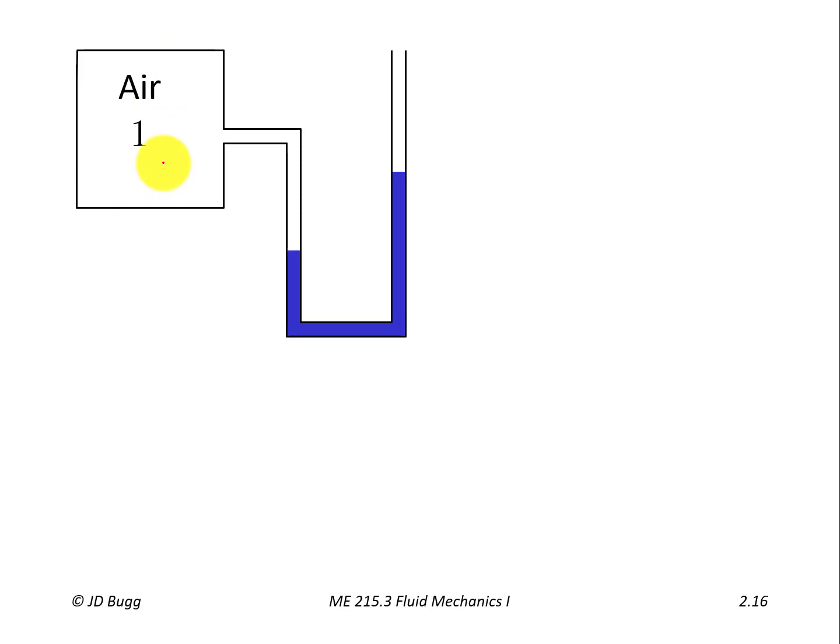If this was at a pressure lower than atmospheric pressure, then the deflection in these two legs of the manometer would just be switched. Some things that are important here: the distance between these two surfaces. Typically that would be read off of a scale that's mounted behind these manometer legs. There'd be a graduated scale so that we could actually read off this distance h conveniently. And I'm also going to label these 2 points here. This air-manometer fluid interface I'm going to label A, and this manometer fluid-to-atmosphere interface I'm going to label point B.